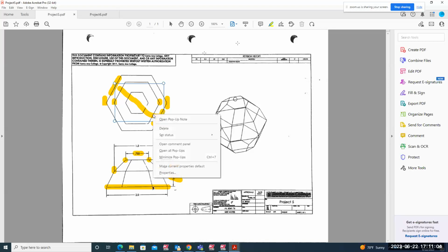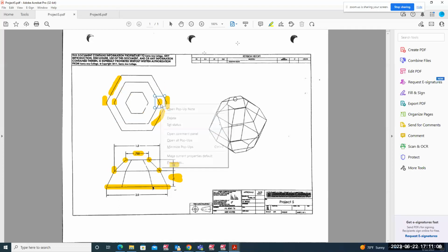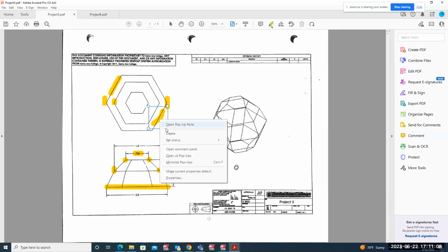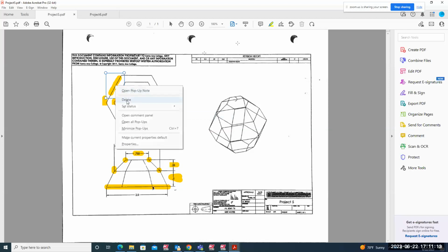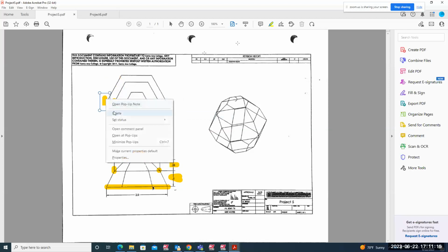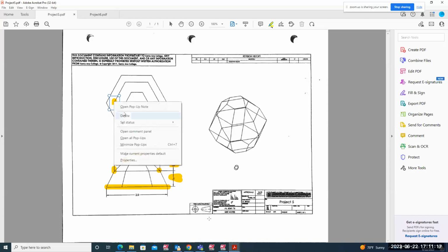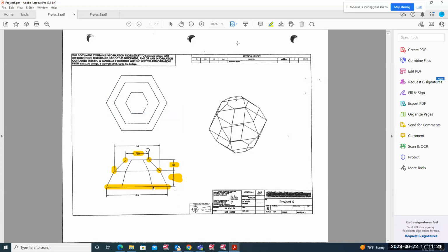So keep that in mind, that when we're going to draw this hexagon, the option we're going to have is either distance across the corner, or you have a distance across the flat. So the option is distance across the corners. All right, so let's go ahead, go to construction plane top and create this first hexagon at Z0, and the distance across corners is 2 inches.